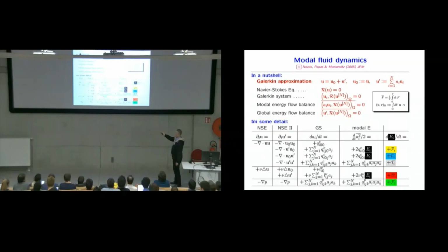There's an irreducible term, essentially this is the essence of turbulence, which leads to the transfer term, and dissipative term, and some other terms. You see that the modal production, convection, and dissipation scale are proportional to the fluctuation energy in each of the modes, and the Galerkin system essentially determines something like the gain, and these nonlinear terms are the ones which are the troublemaker.